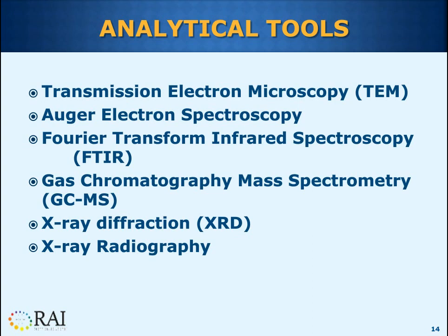Because nylon 6 and nylon 6,6 have different melting points, I know if the sample is nylon 6 or nylon 6,6. Whereas with FTIR alone, I could not make that distinction. So that's a good example of the need to use complementary techniques to find out what I need to know.